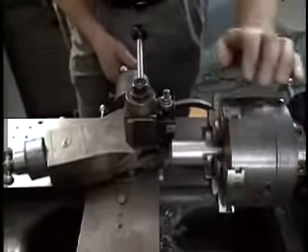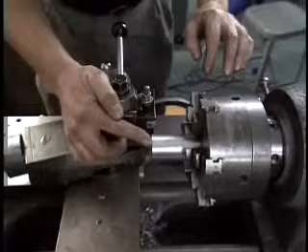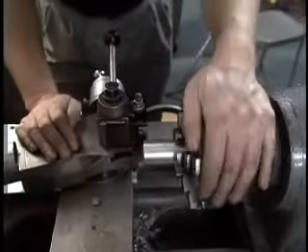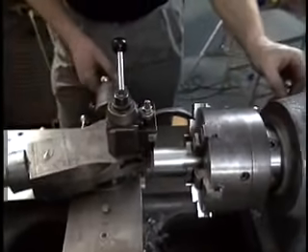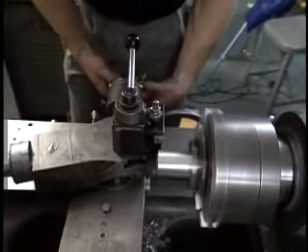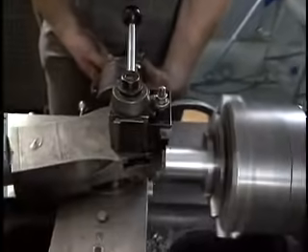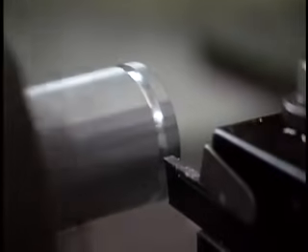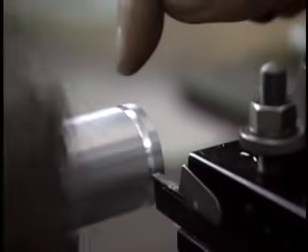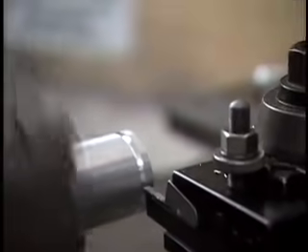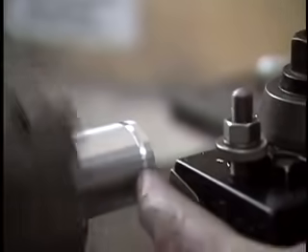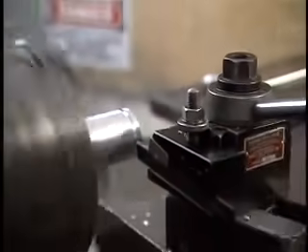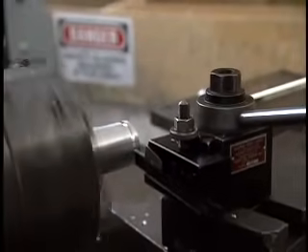Turn the chuck to make sure that nothing interferes either between the tool and the part, or between the chuck, particularly between the chuck jaws and the rest of the machine. Turn the machine on and feed the part slowly. It's reasonable to cut a groove of about this depth dry. Cutting any deeper puts more and more of the edge of the tool into contact with the sides of the groove, generating heat. So as you go deeper into the part, it's more and more important to use some cutting fluid.